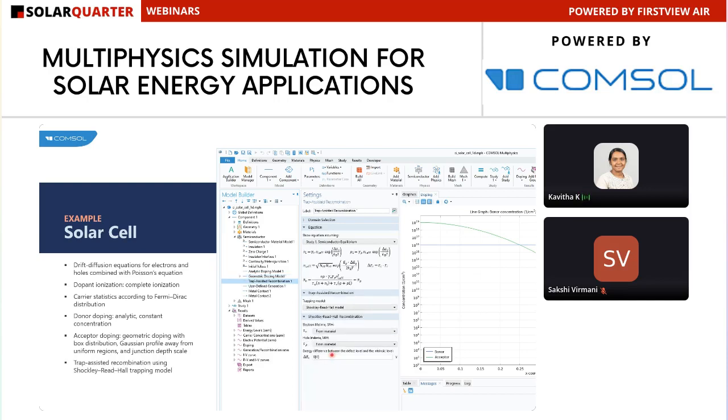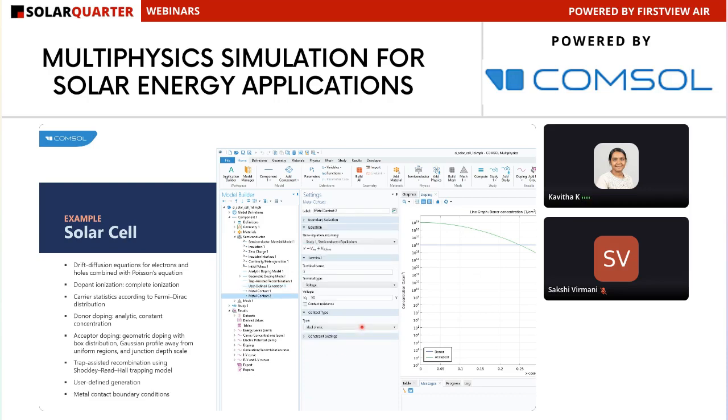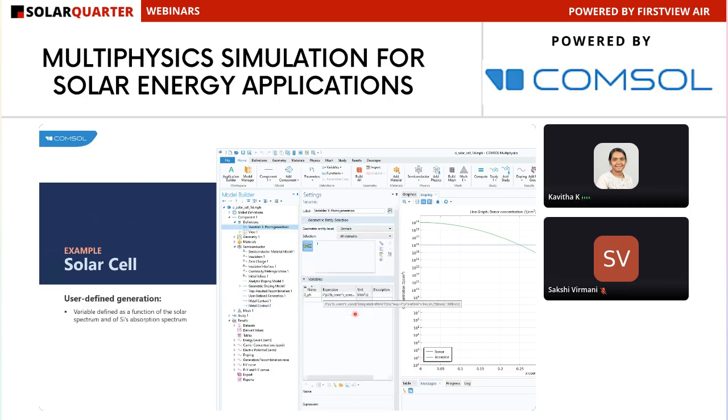So when the sun rays fall on the PN junction, they are going to generate electron-hole pairs. With the help of trap-assisted recombination, the well-known Shockley-Read-Hall model, we are considering the electron lifetime and hole lifetime. The generation rate depends on the material properties that you choose. Then you define the user-defined generation rate for the electrons and holes. Then you apply the biasing conditions using the metal contact boundary condition.